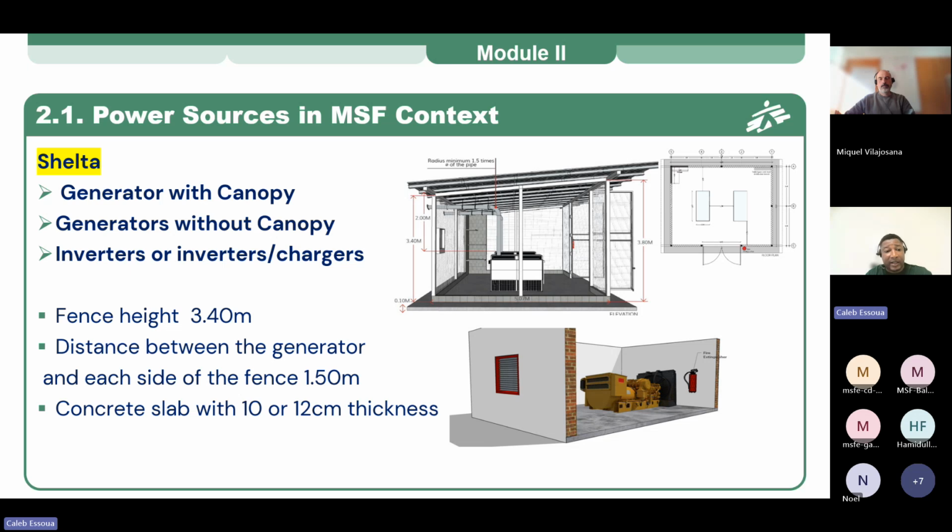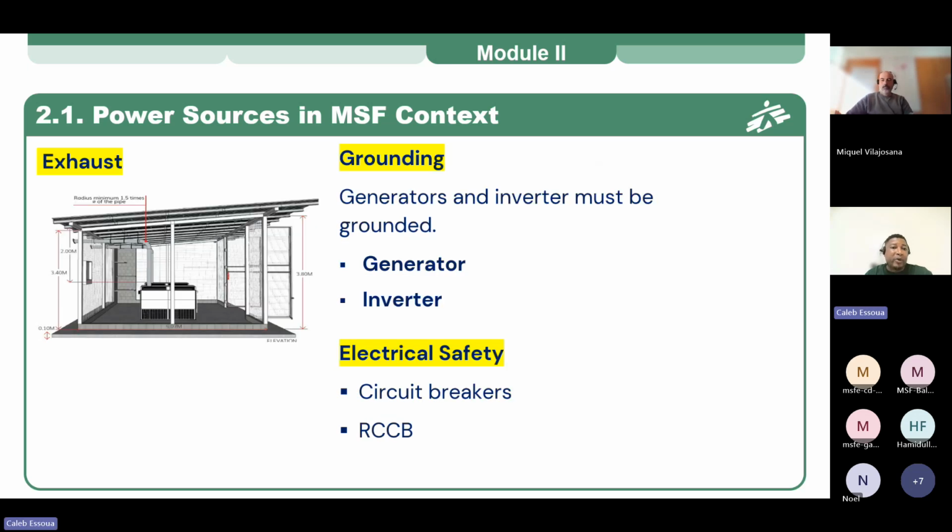So this is basically the things. I already talked about this one, but for the electrical one, we should have this main distribution box close to the generator so that we can connect it. And this distribution box must have the few things that we talked about, okay? The protection of people and the protection of equipment, which are the most important things inside. And then the other things can come in.